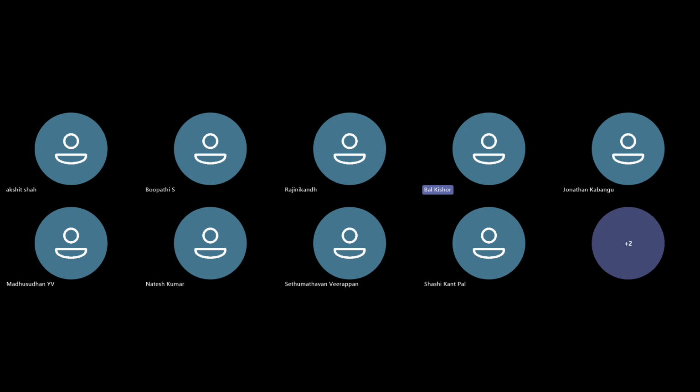It is asking for a stop time. Let me give, let's say, 10 millisecond. I'll start saving data from a starting point of 0. If you want, you can flip the windows by this. Press the space bar to fit the complete circuit. So this is how it will work.